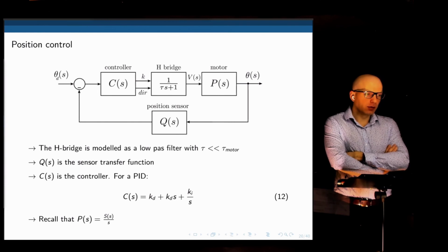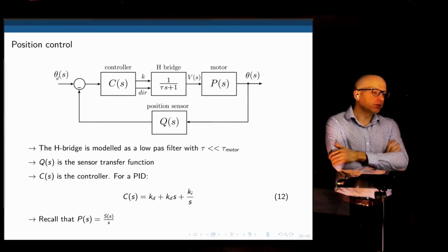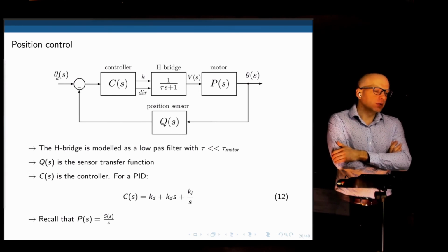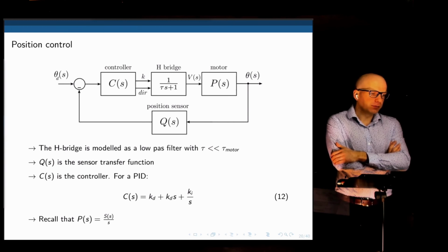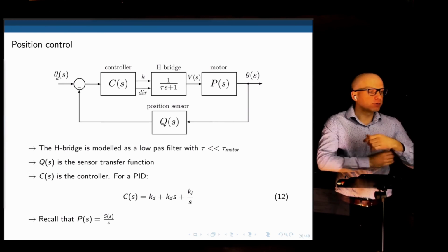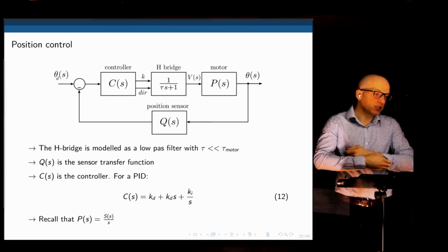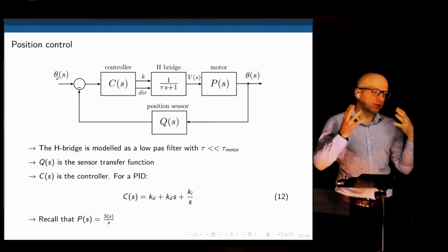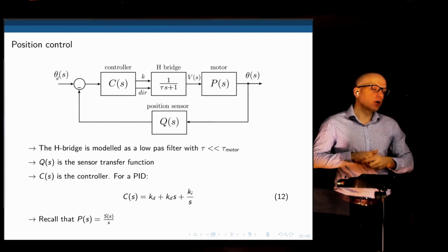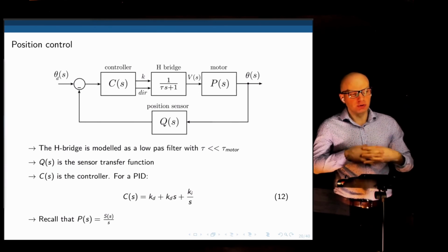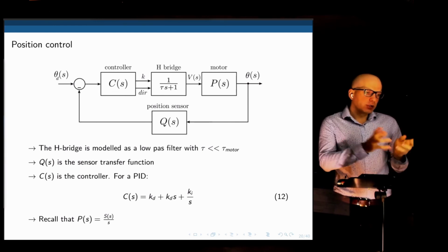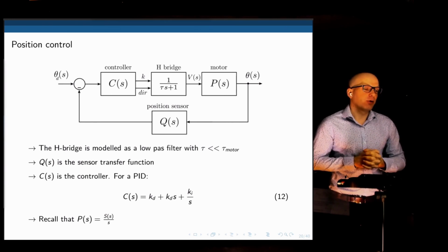Steady state error is 0. There we go. The steady state error is always 0. That's the function of the integral gain, it is always to eliminate steady state error. So it will be part of a controller. Certainly in practical applications, it will be there. It will always eliminate steady state error regardless of the value of ki, but it comes with the drawback of creating overshoot and may create instability. Overshoot then can be compensated for by adding the derivative gain.